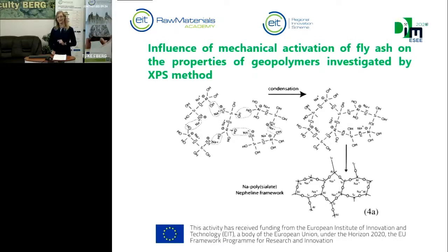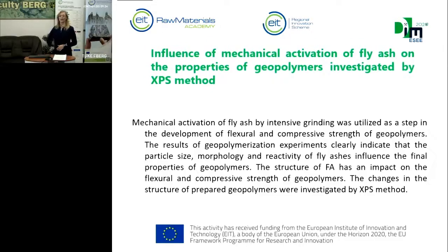This is very interesting because the creation of this chain is very important in the creation of geopolymers. Mechanical activation of fly ash by intensive grinding was utilized as a step in the development of flexural and compressive strength of geopolymers. The results of geopolymerization experiments clearly indicate that the particle size, morphology, and reactivity of fly ashes influence the final properties of geopolymers.